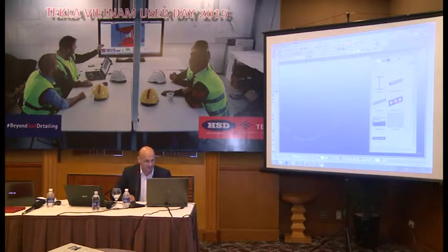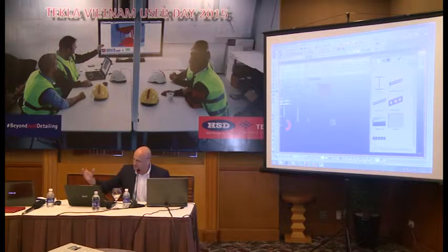Same thing with the direct modification now, you can pick that up and drag it to be any size as well. So you can quickly see the radius. Same if you draw a construction line, let's say a line from there to the 3-point there. Click on that, again you can pick this up and drag it down to be any size like that. It also works for the grid lines actually, so you can pick the grid lines and move them. So any object now is beginning to move more towards this. You need to select the individual grid line actually, but if you click on it, the individual grid lines you can just move them with control. Okay? So bear that in mind because the whole system is moving more towards that way of working.